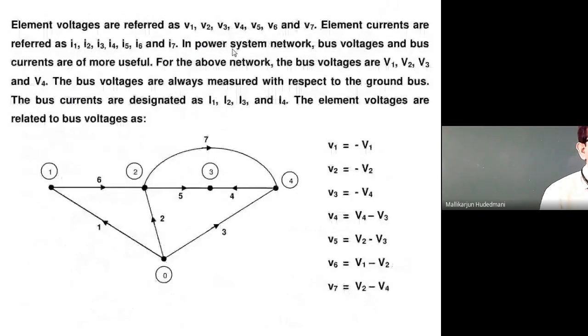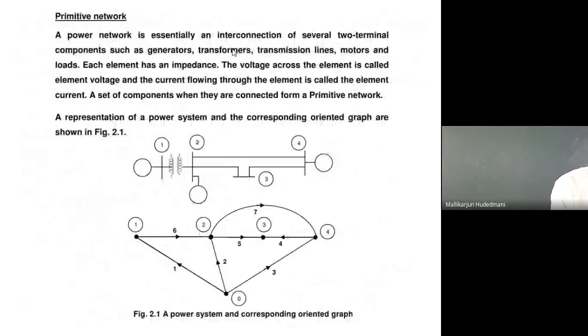This is the problem. This is the electrical power system layout whose Y bus I want to obtain by the singular transformation method. Then for this electrical network, I should check how many buses are there. Physically, if I count 1, 2, 3, 4 and ground is hidden here. So there are physically 5, but practically you will find 4 in the representation. Ground is a hidden reference. Then it is represented at the bottom of the presentation, 0 as a reference, 1, 2, 3, 4 as distinct buses.